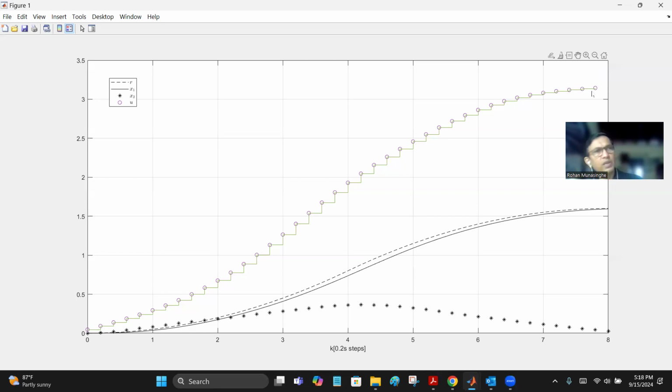You have seen probably this in PID controls also, right? When the system is settled, there's no error. So therefore, the proportional controller is zero. It doesn't do anything. When there's no rate of change, the derivative control is also zero. It doesn't produce any control signal. But there is a big non-zero control signal produced by the integral controller. And that is what keeps the state at that reference level without letting it fall down to zero. So integral control is very important, therefore.